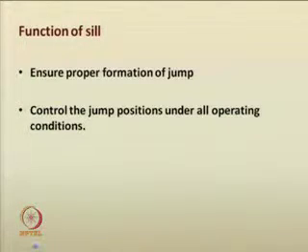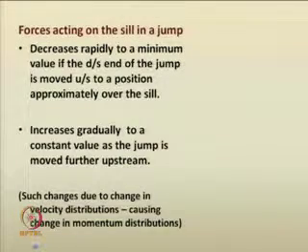So, what are the various forces? You can see the different forces acting on the sill on a jump. The force decreases rapidly to a minimum value if the downstream end of the jump is moved upstream to a position approximately over the sill.